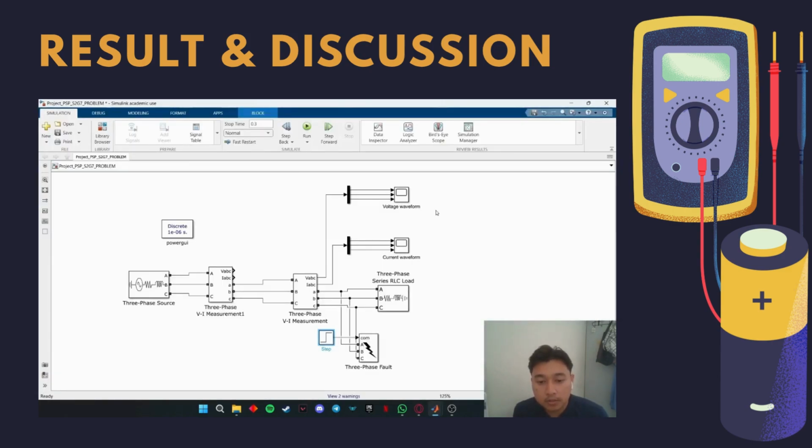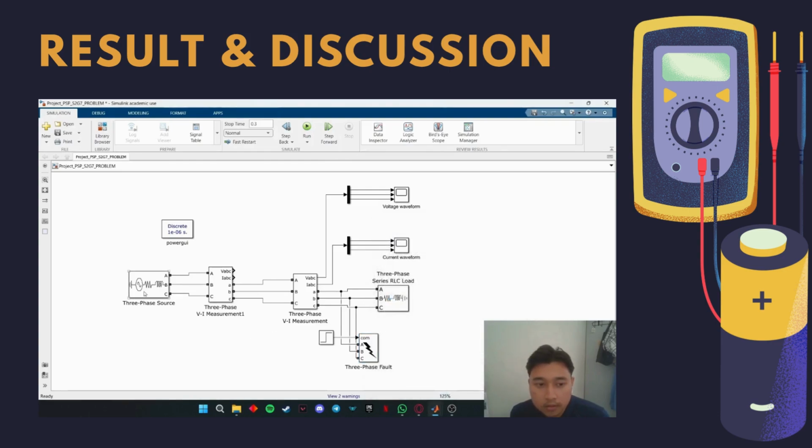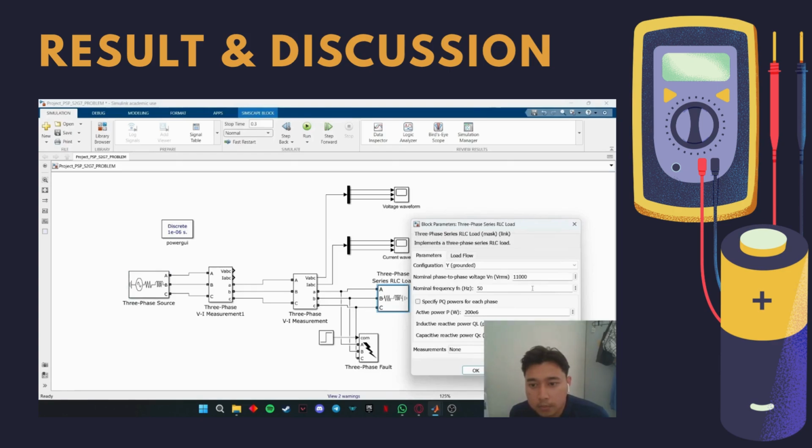For the next one, we need to simulate the balanced fault condition, where we put the three-phase fault between the three-phase VI measurement and the three-phase series RLC loads. As we can see here, we set the fault between phase A, phase B, and phase C. Then we set the three-phase source phase-to-phase voltage, which is 11 kilovolts at a frequency of 50 Hz. And the three-phase series RLC load, we also set the same, which is 11 kilovolts and 50 Hz.